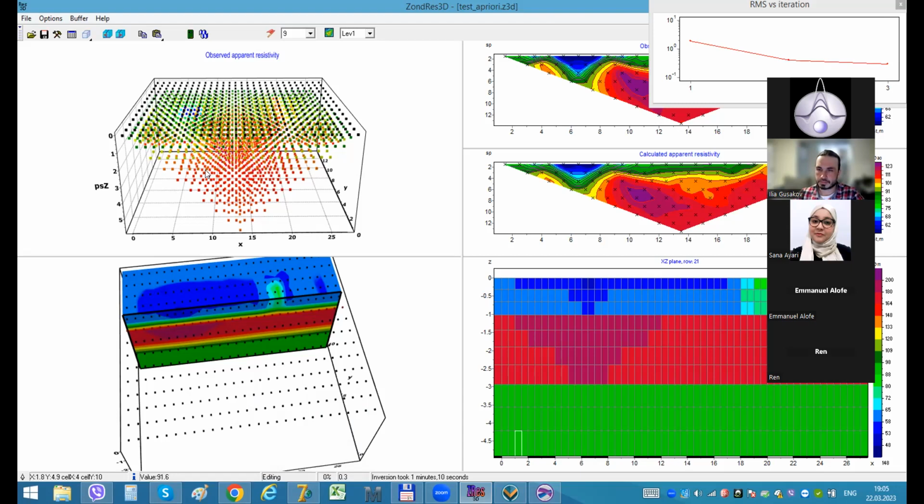Yes. And a question about vertical electrical soundings. Yes, I see your question, that you have 80 VES points with an average spacing of 1 kilometer between them. No, you couldn't do a 3D inversion for very big spacings between soundings. The same thing for ERT. If you have a very long distance between lines, it becomes not 3D, it becomes 2D.